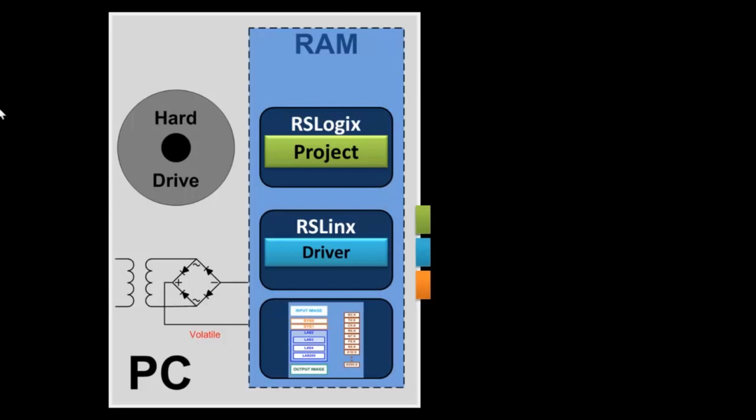In this case with Emulate, because the Emulate framework is now defined and has an address or a location number 0 through 31, you can open up RSLogix, you can do communications, Who Active, and when you open up the browser, it will find the Emulate framework because it's made to appear now like it is a device out there on a network, and then you just go online with it.